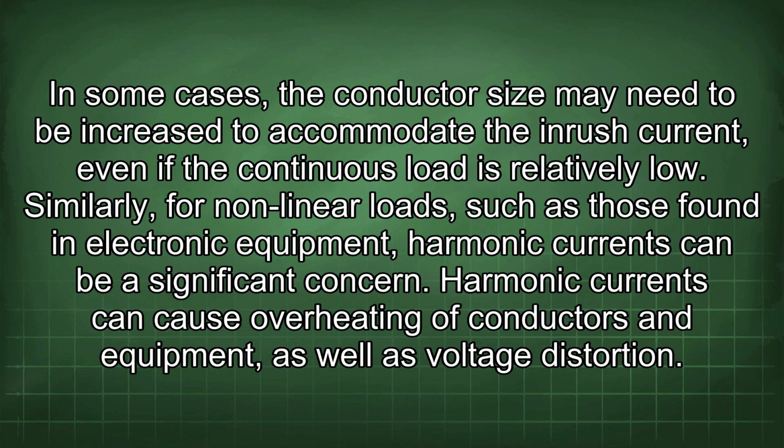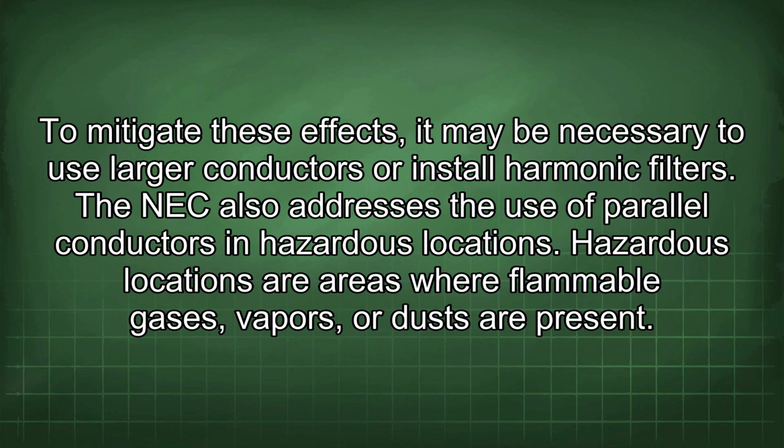Similarly, for nonlinear loads, such as those found in electronic equipment, harmonic currents can be a significant concern. Harmonic currents can cause overheating of conductors and equipment, as well as voltage distortion. To mitigate these effects, it may be necessary to use larger conductors or install harmonic filters.